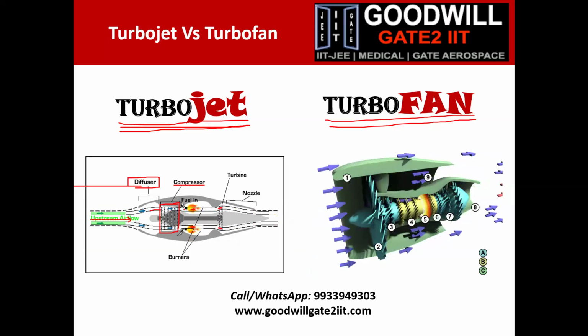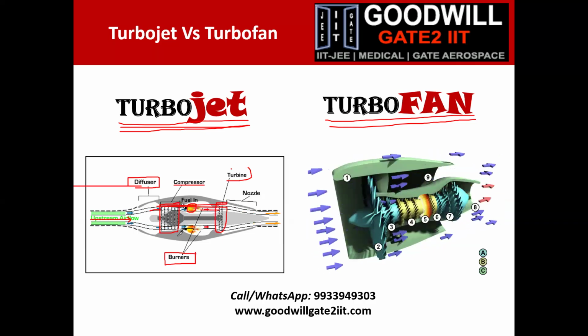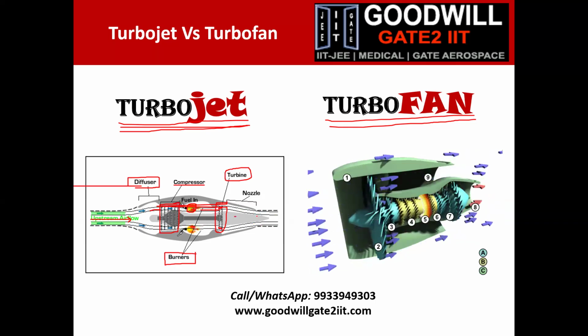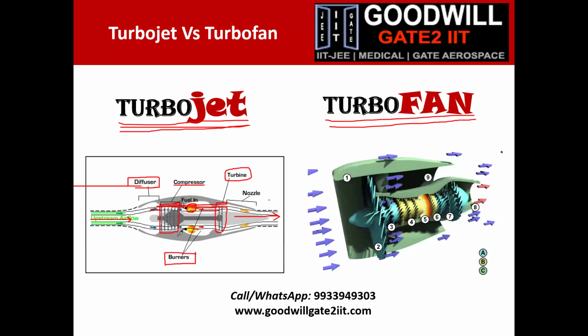Then after the compressor, air enters into what is known as the burners or combustion chamber, in which we typically burn fuel. You can see the burning happening here. Then this burned air enters the turbine, this portion, which is basically producing work for your engine. Then these hot gases come out from the nozzle. Now the nozzle can be a CD nozzle or a converging nozzle. So this is a basic layout which looks very simple, right?